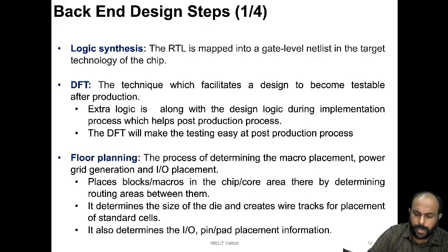So you have a particular design, and alongside that design, certain extra logic is inserted so that post production testing of the design logic becomes easier. It gives a certain amount of controllability and observability to your design. So the purpose of DFT is to insert additional logic into the design so as to make the testing of the chip easier post production.